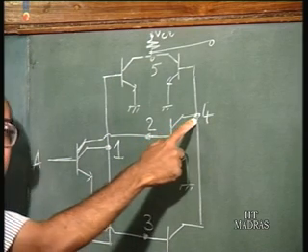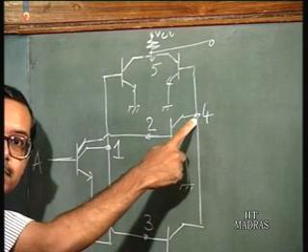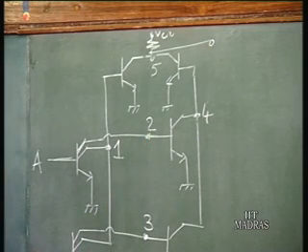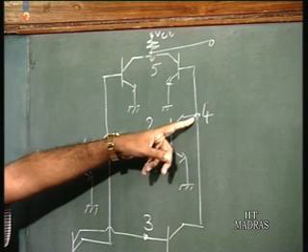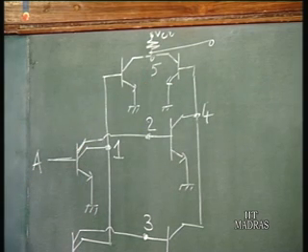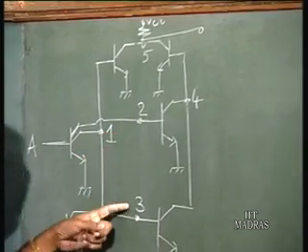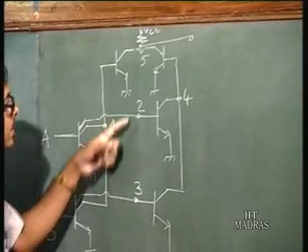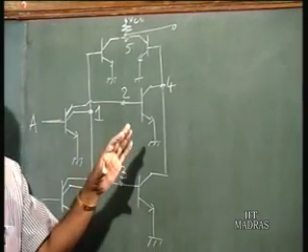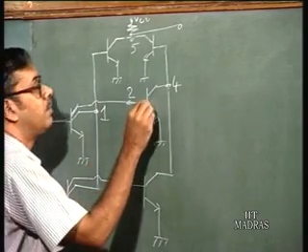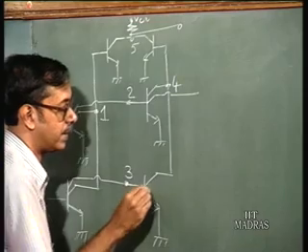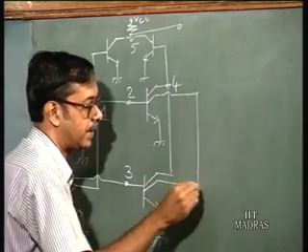You must take the output from this point. Actually, it is 4, you know. So, basically what you do is you cannot take the output from here, because this voltage cannot rise to more than 0.7 volts. So what you can do is, you have to make another NOR gate, and do that. Basically you can take another collector here and connect it here.